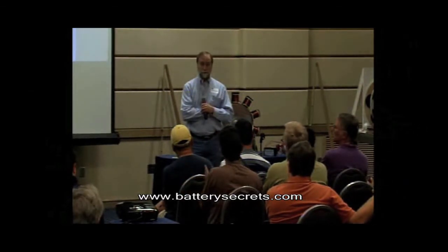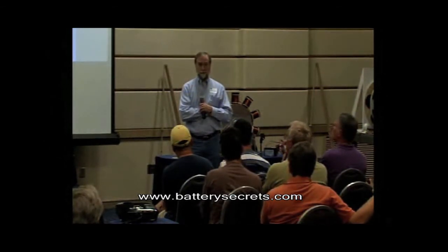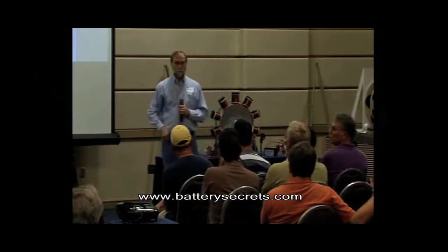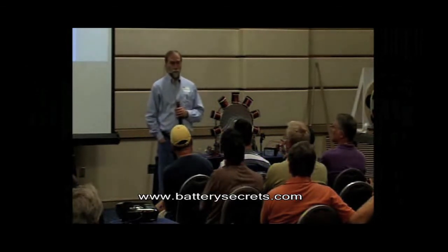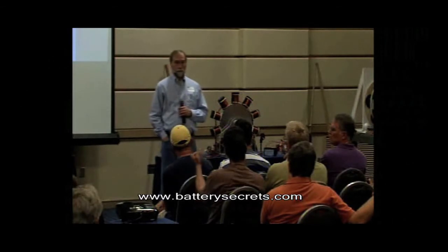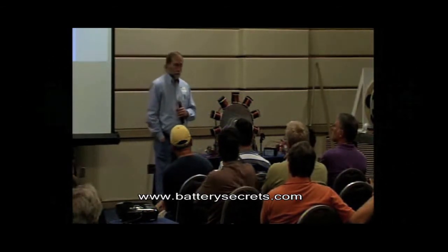Now, looking at the fact that my negative plates are 25 years old and they're nice, big, and fat, and that's what we're sacrificing. No, you're sacrificing the positive. Correct, but the negative plate is really big and fat and untouched. Right. And I thought, what about if we were to drop that right down and then charge her backwards? You can. Would that not be a good thing?